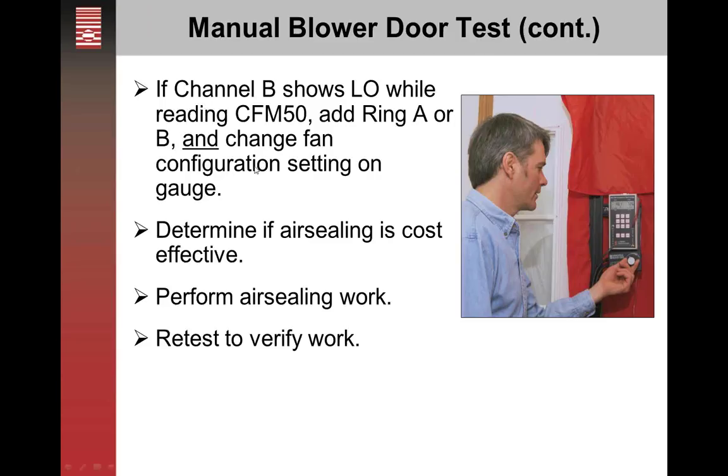By measuring and figuring out what the airflow is, it will help us determine if air sealing is actually a cost-effective function. We want to use the blower door during the air sealing work because it helps identify, have we hit the big holes? Have we done enough to actually make a difference on this house? And then we do that test again when it's all done to verify for the homeowner that we have good results.